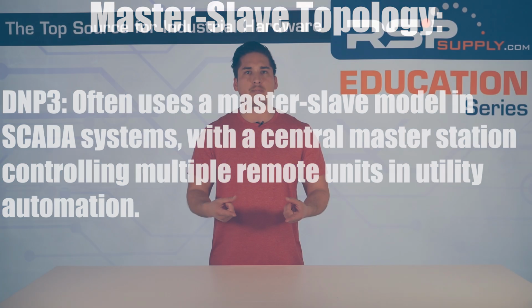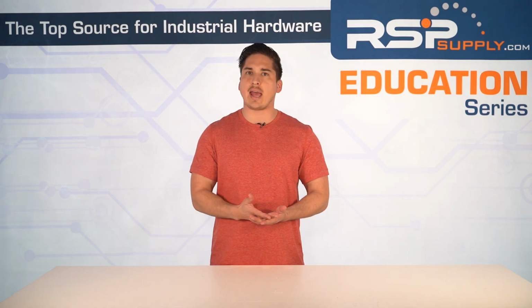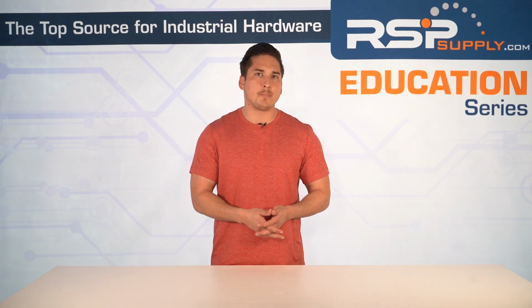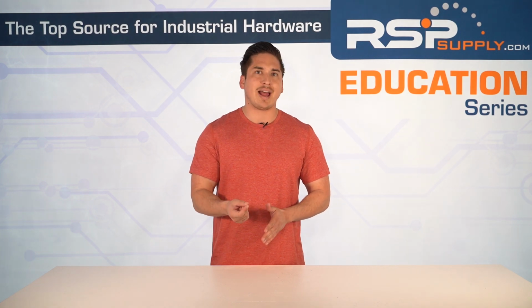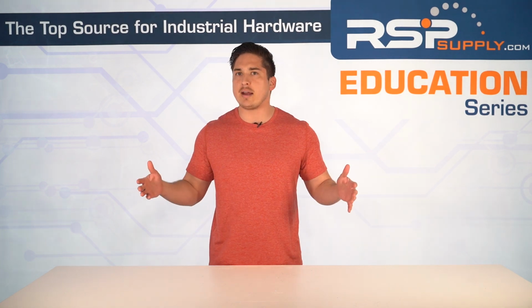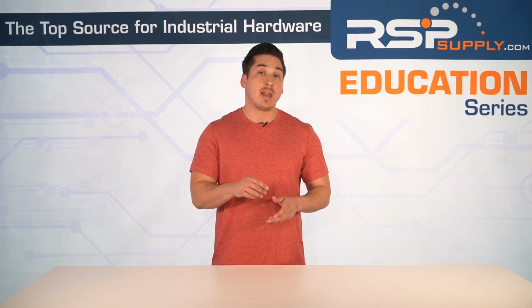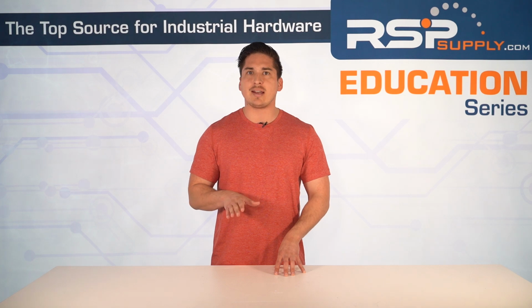So we covered the key protocols like Profinet, Ethernet IP, EtherCAT, Modbus TCP, OPC UA, DNP3, and HART. And we broke down how speed, topology, and use case are going to impact your selection. From real-time motion control to large-scale SCADA, choosing the right protocol is all about matching the tool to the task. Up next, we're going to show you how to design a mixed protocol network that keeps everything connected and running smoothly.